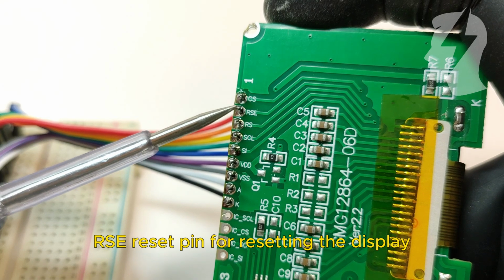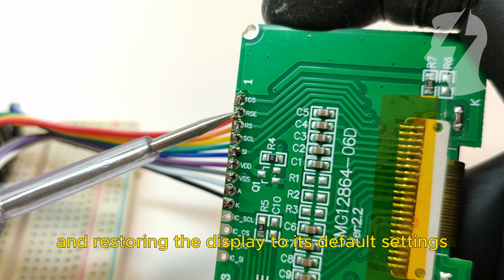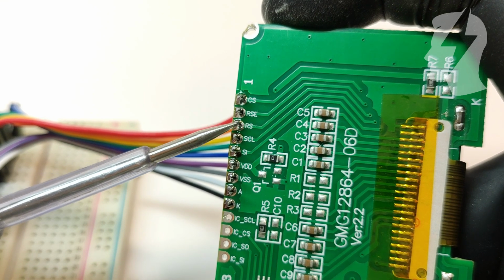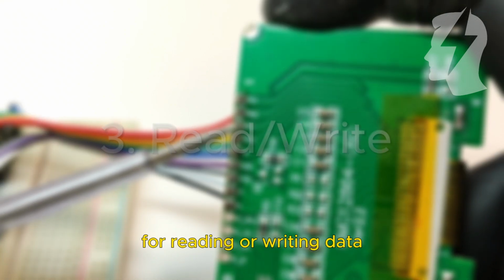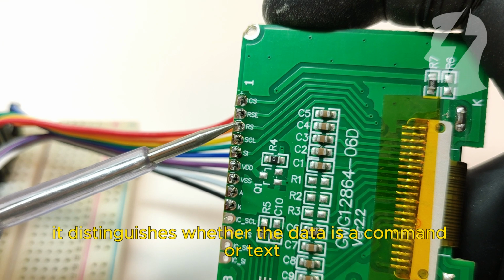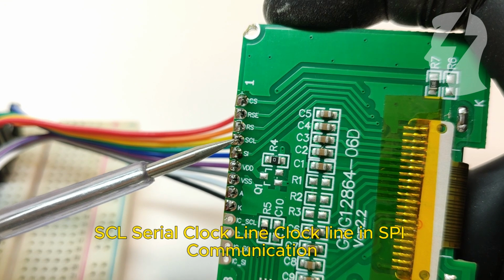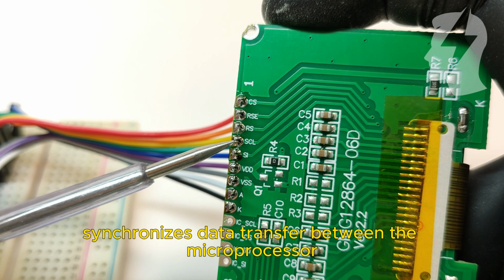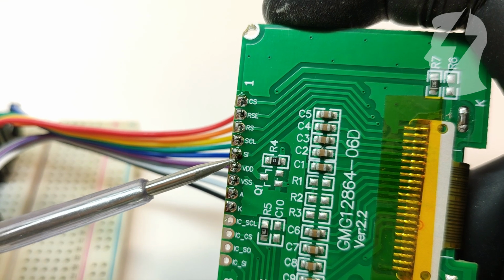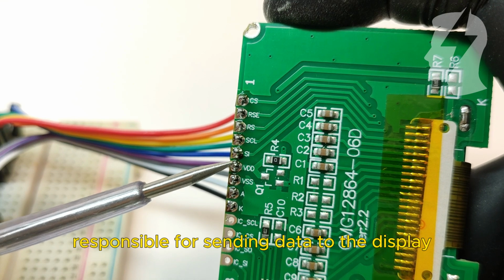RSE, reset. Pin for resetting the display. Used for initialization and restoring the display to its default settings. RS, register select. Used to select the register for reading or writing data. It distinguishes whether the data is a command or text to be displayed. SCL, serial clock line. Clock line in SPI communication. Synchronizes data transfer between the microprocessor and the display. SI, serial input. Data input line in SPI communication. Responsible for sending data to the display.